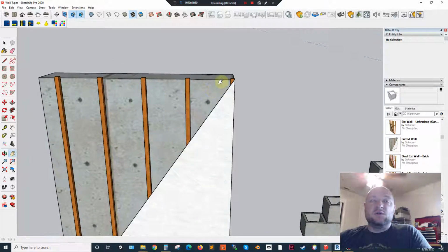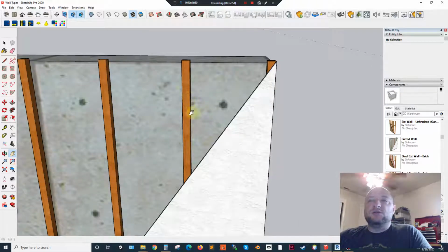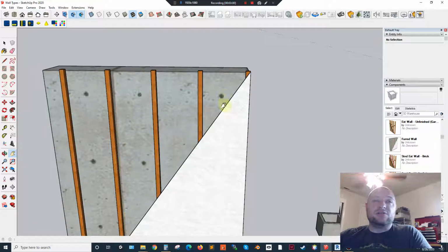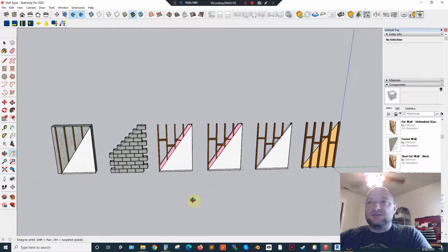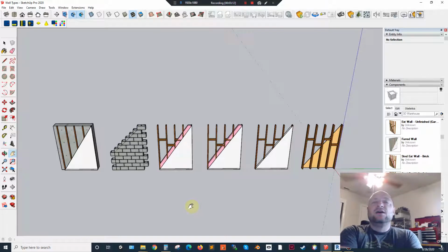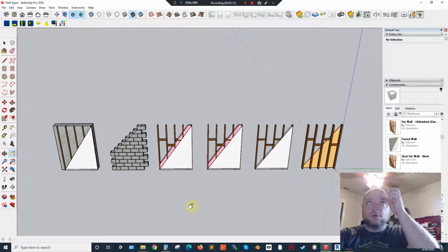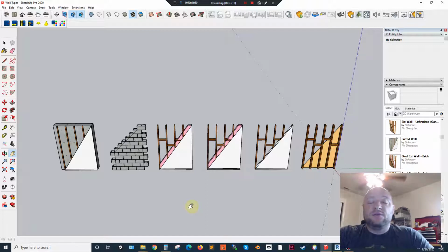This is when you would have a precast concrete structure. You would use mounting holes to place wood into that, and then possibly even have rigid foam insulation in between these areas, and then you would put your gypsum over that. So I'm going to have this file online for you guys to access. It's going to have basically a couple of these walls, and I'm going to expand on this as we get further into Revit. We'll be discussing floors, ceilings, and how those all work together.